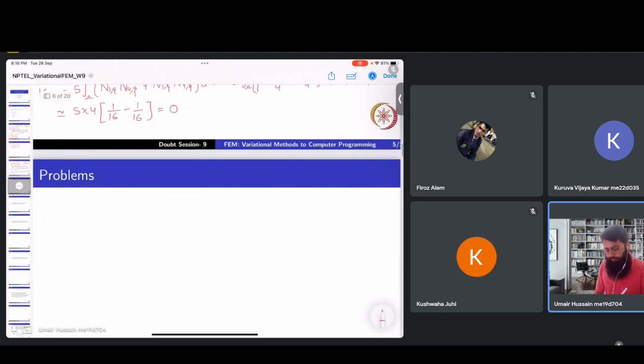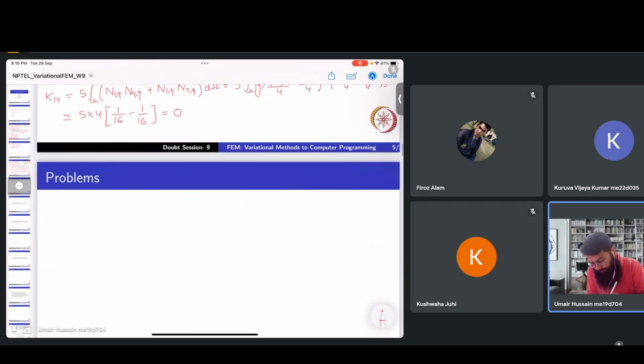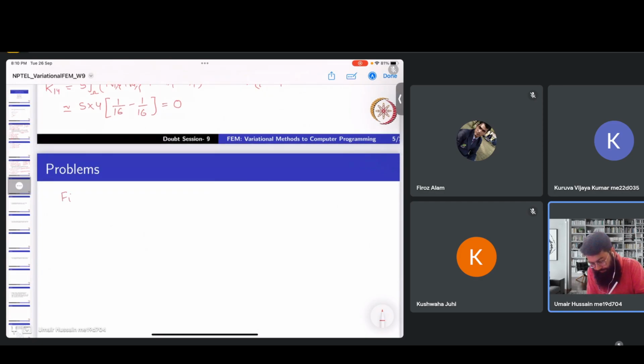Okay, we can try for some force matrix values. Oh, this was straightforward. So F1 would be 1 by 4, 1 minus eta, 1 minus psi, 1 minus eta, and we apply the Gauss quadrature. So eta equals 0, psi equals 0, eta equals 0 would give us 1 into 1. So we just have 1 here.